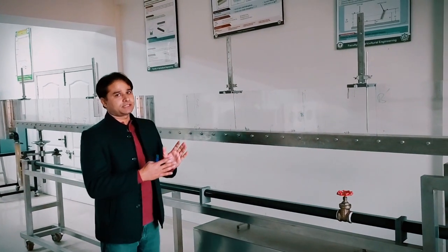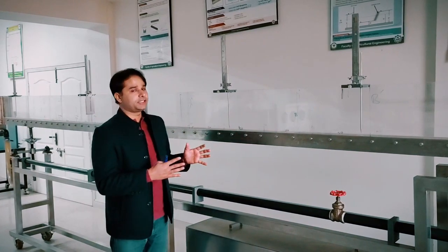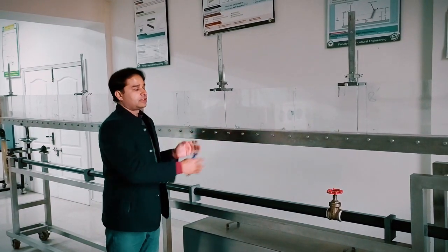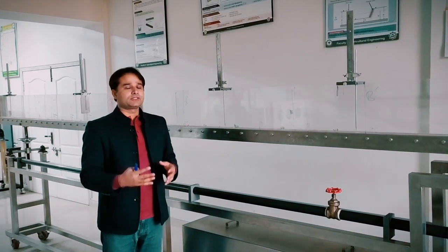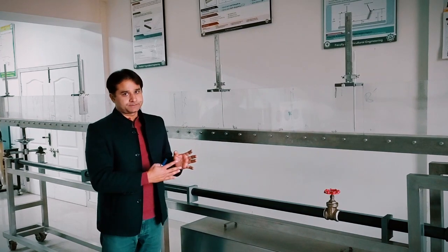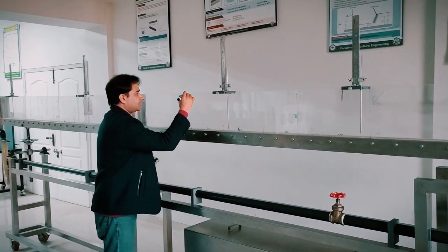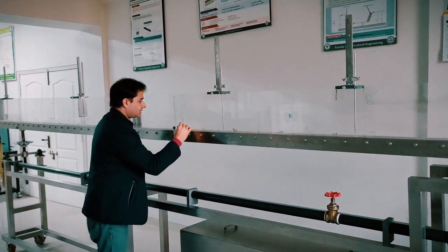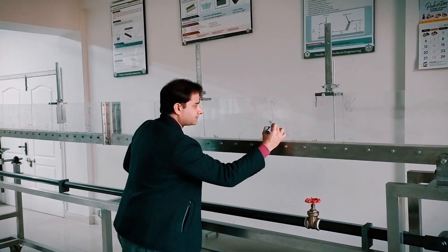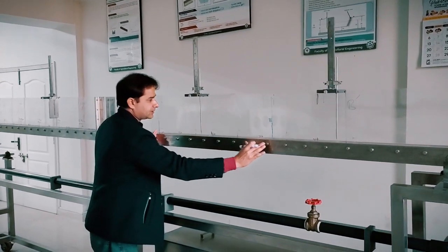We call that section the channel reach. In that channel reach, the cross-section area should remain similar along the channel. Similarly, we can call that section a prismatic channel. After selection of the fixed cross-sectional area, we have to mark 2 points on the reach. We have to measure the length of this reach.